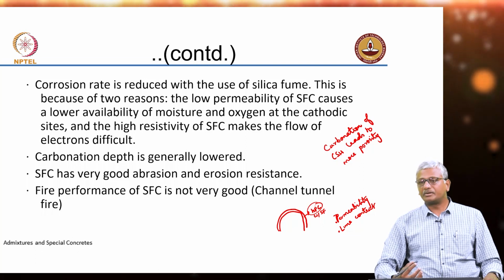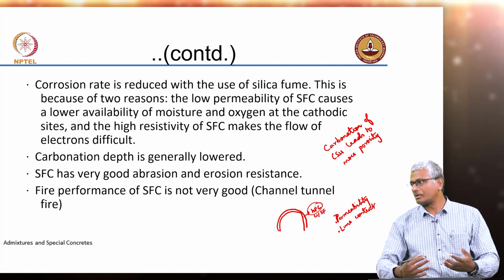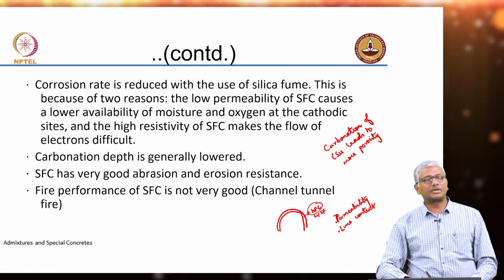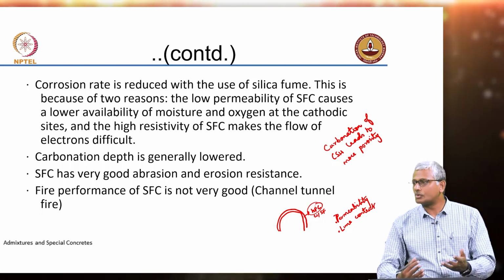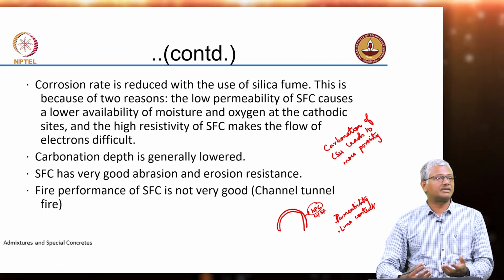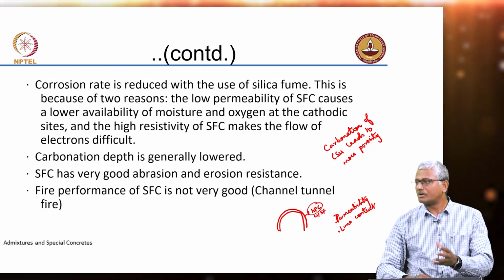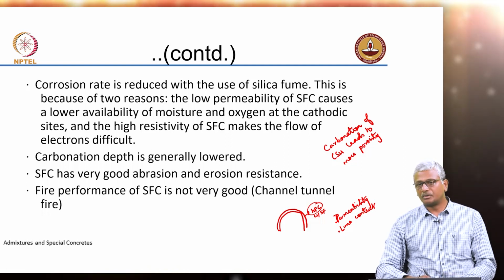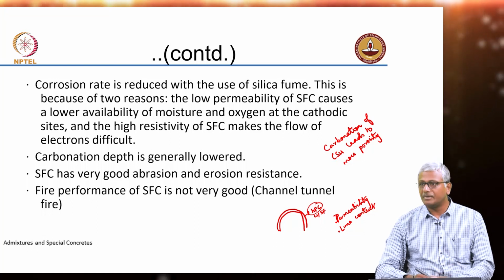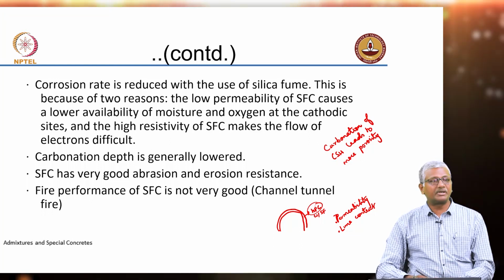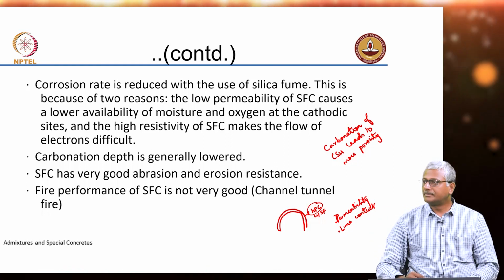Exactly. When concrete heats up, water will convert to steam. The steam needs to come out of the concrete, like your pressure cooker, right? The weight goes up and the pressure gets released, and that's exactly what's happening here. There's no release of pressure that's possible in concrete that is extremely dense. Concrete which has very little porosity may not have sufficient passage to push out the water or the steam. Because of the pressure that's getting built up, your concrete starts getting stressed and completely spoiled, right?